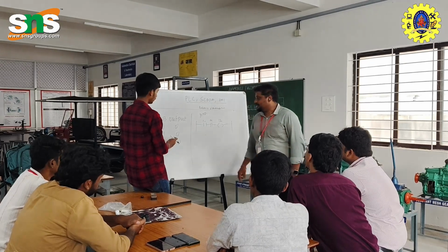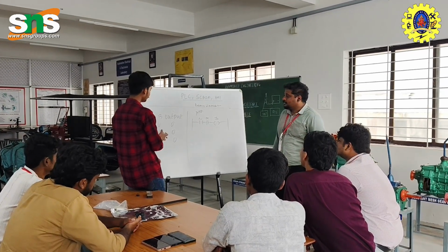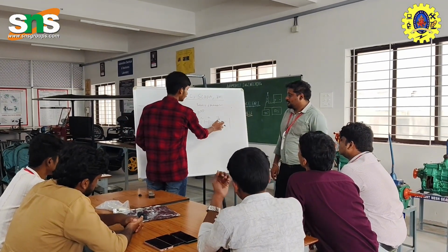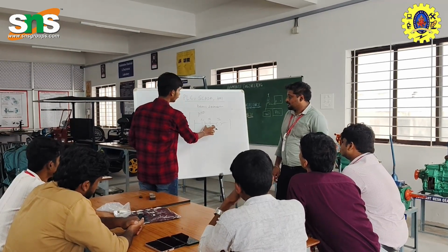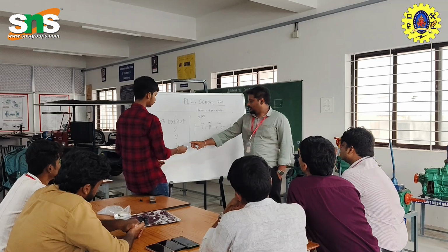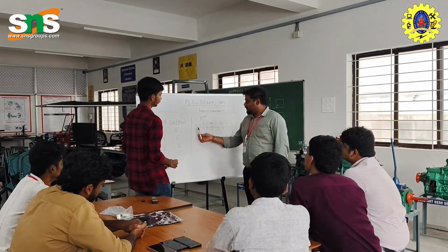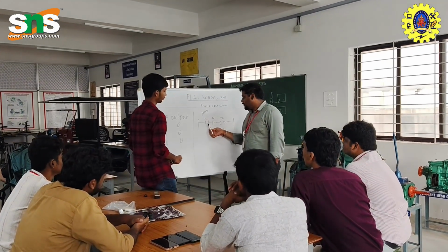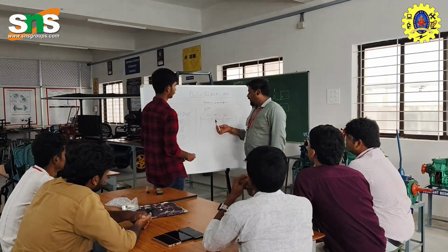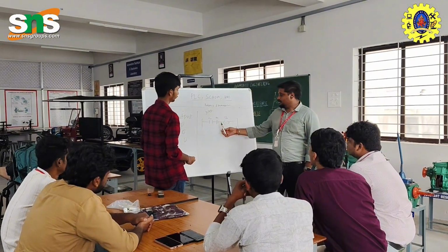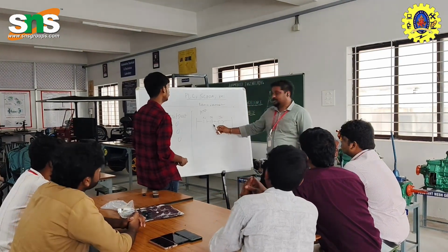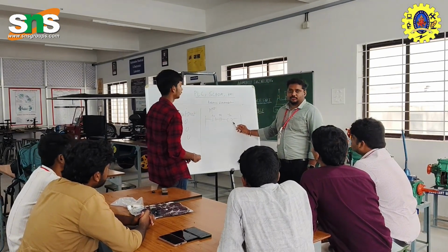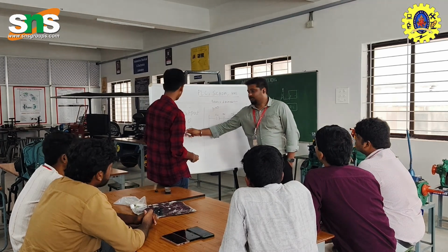Moving to the second condition. In our second and third conditions, even if either one of the input devices is turned off, our output will still be in the off state, because we need both the input devices. For example, if X0 is turned on now, current flows from positive up to X1, but after X1 it will not flow, because X1 is 0, so it does not allow current flow in this state. Then the output will be 0. Likewise, 0 1 1 0.